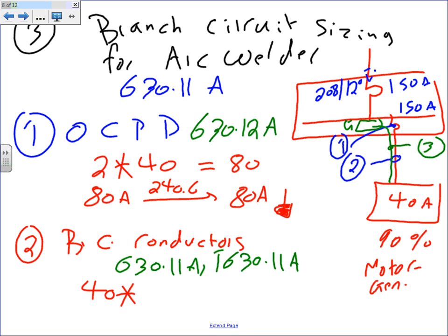So what's the multiplier for 90? It's 0.96 for motor generator. That's the multiplier from the table. Let me match it to what we have at the beginning: the first one was motor generator. Good, so for 90, the multiplier would be, like Chris said, 0.96.